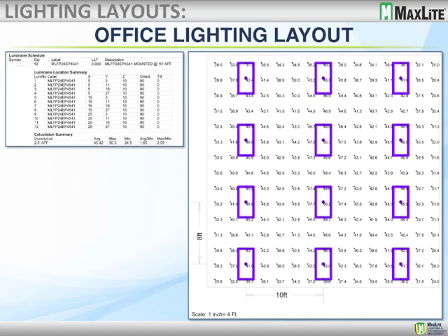When you do not give us any reflectance values on a project, you let us know what it is. If it's an office, we usually do the standard 80, 50, 20. If it's a warehouse, we'll lower the reflectance values to 50, 50, 10. And if there's racking, we also put all that in. We put the obstructions in. So with this, there were no other obstructions.